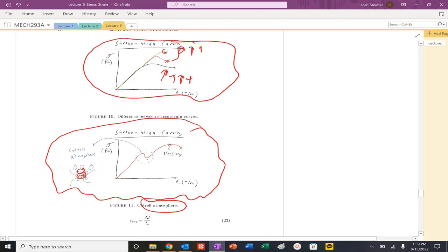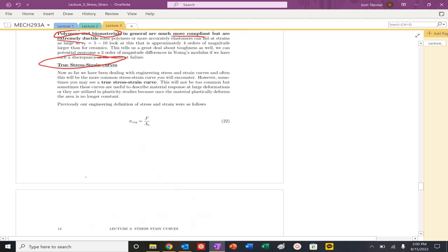So you get this dip and then build up again, because those atoms will again seek to pin those edge dislocations. But we'll get to that feature, and we'll get to the diffusion of interstitial atoms near edge dislocations and the interaction between edge dislocations and other 0D defects in later lectures. But cool feature. All right, true stress strain curves.